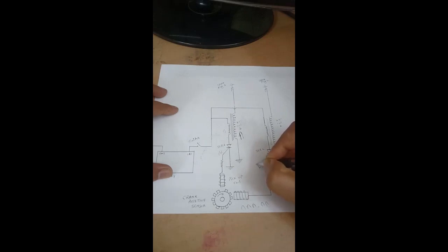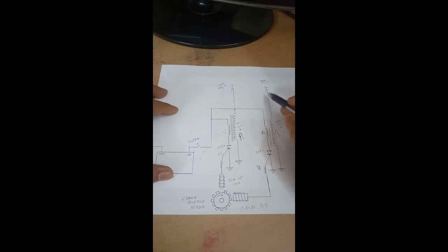That drop in voltage is sensed by this pickup coil, and SCR number 2 goes into conduction, conducting the current heavily. It again produces a small 12 volt pulse here. As this is a step up transformer, it again produces a large pulse in the secondary, and a spark is generated in spark plug number 2.